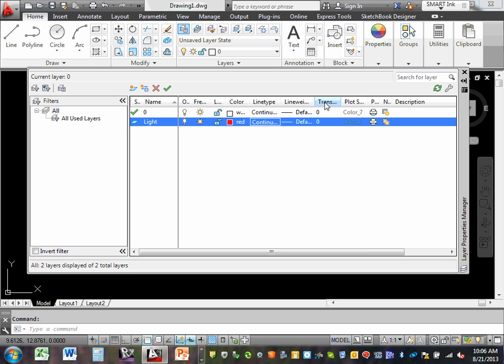Now, that's the second important thing, guys. Do you see that printer here? It will tell you, would you like anything on this layer to be printed? Or would you like it just for your FYI information only? When you send it to the printer, it would not print. So click on the printer, guys. Do you see that little red X on it here? Everybody see that? If you see that icon next to the layer, that will tell you, by the way, this layer is for FYI only. So when you're looking at it, you see it, but when you send it to the printer, it wouldn't print.